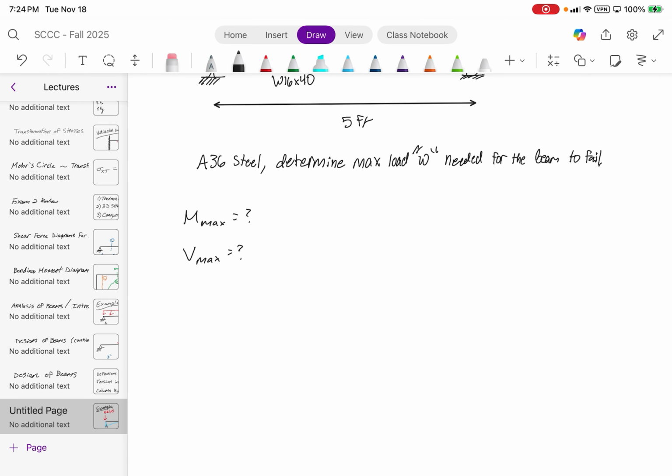Well, first of all, let's check bending. What is our bending stress equation? If you guys can't tell me, this is a problem. Bending stress equation. Sigma is equal to M over S, but what's our unknown here? M, because we know the stress and the section modulus, right? So we rewrite this to say stress times the section modulus.